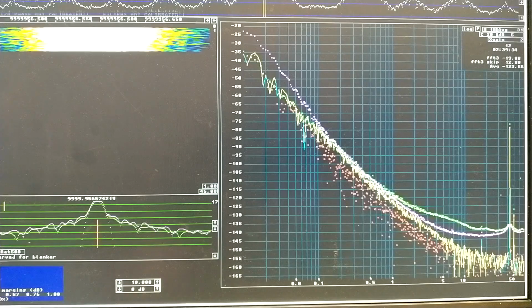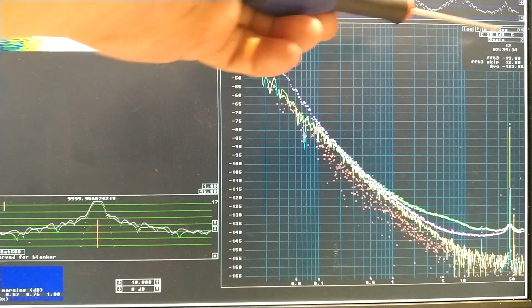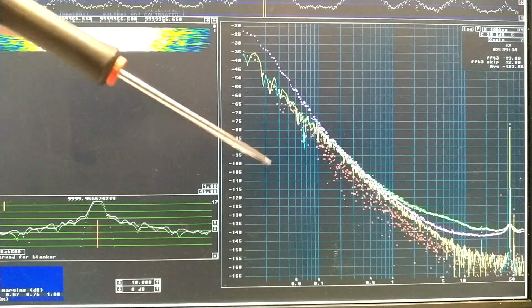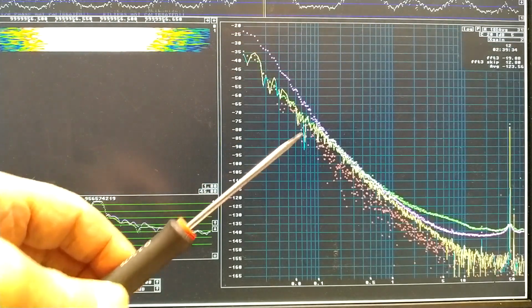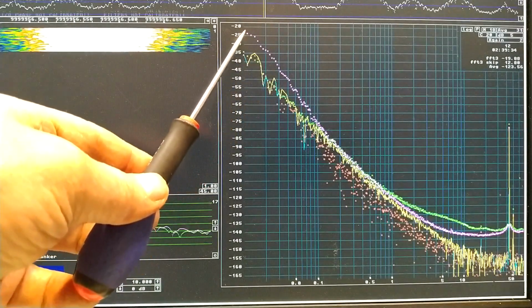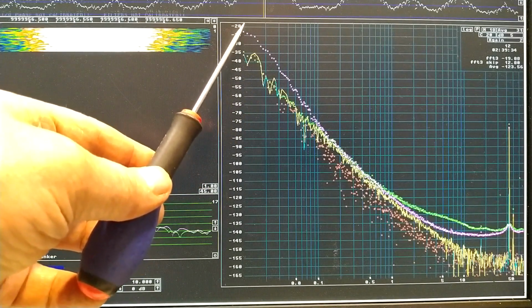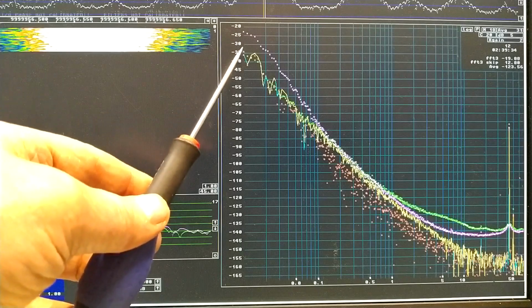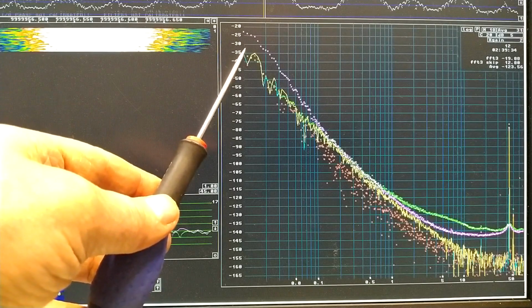I have set very slow processing parameters. In 2 hours 40 minutes I have collected only 12 average spectra. The reason is that I now suspect that the excess phase noise of channel 2 is at about minus 23 at 0.01 Hz, while channel 1 is at minus 35.